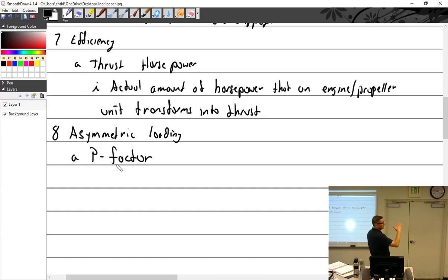But make a climb, and one side is going to flatten out, and the other side is going to get more of a pronounced bite, right? So which side is which? The downward swinging blade is going to have the higher angle of attack. Yes, it's the right side. It's going to want to pull you away. Think about that in a couple of ways. From a pilot's perspective, you've got a bigger bite on this side, so the plane's going to want to go left. So you apply right rudder again.